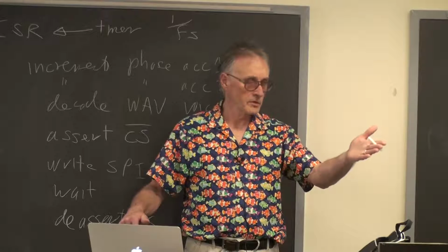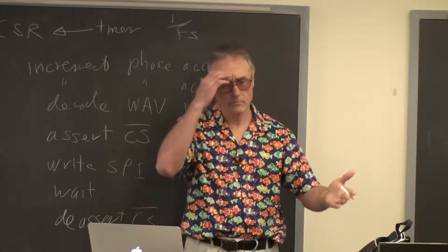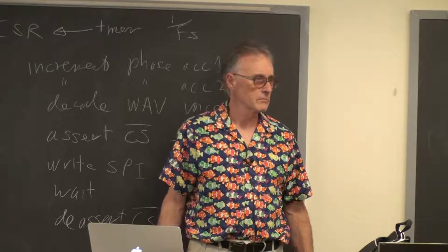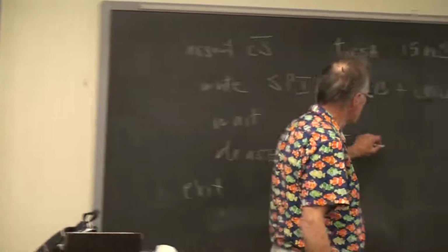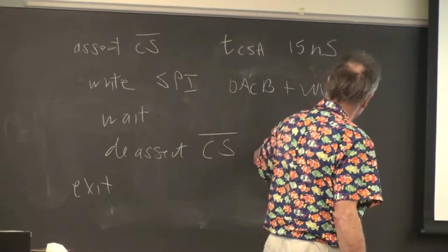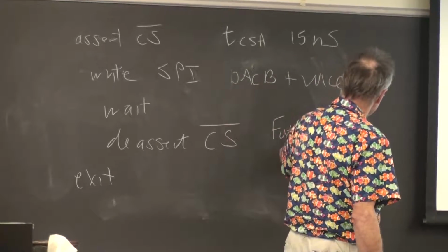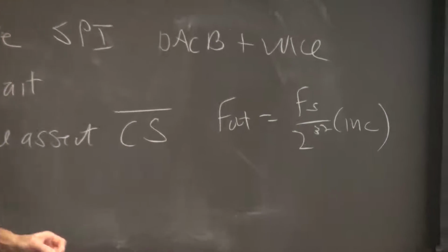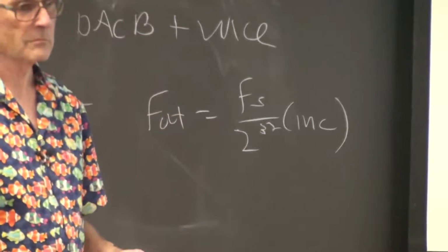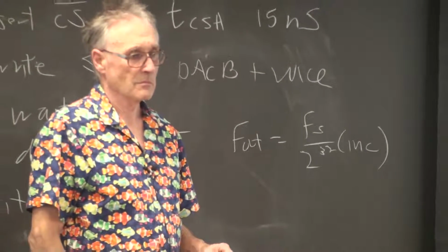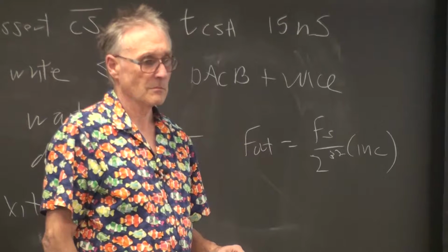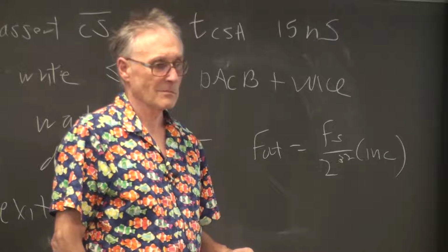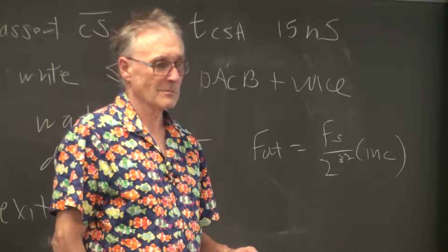Yeah, not about the DMA. Sure. More about the DDS. So, in your DSP code, you use the formula you gave us last lecture, the F out equals Fs over 2^32 times the increment. Mm-hmm. It's just a reverse in the code there. And so I played around with it and hooked this to the scope, and I saw the FFT in the waveform. Uh-huh. And we get something like this, but the oscilloscope doesn't measure the output frequency that we set in the code. I think by default, the DSP code had like 100 hertz, and the scope showed like 140. And then when we tried playing around with it, it just didn't agree at all.